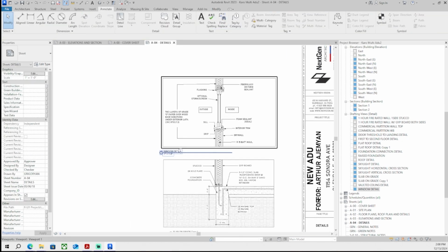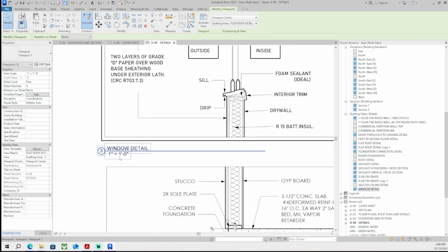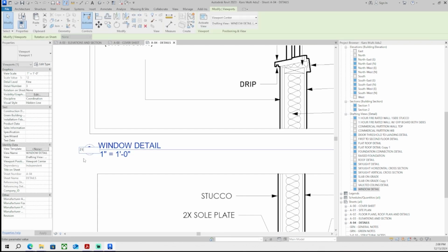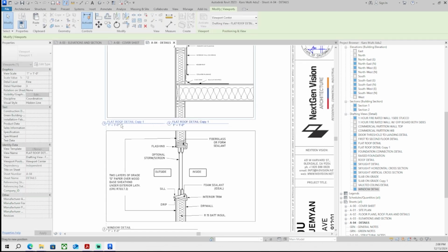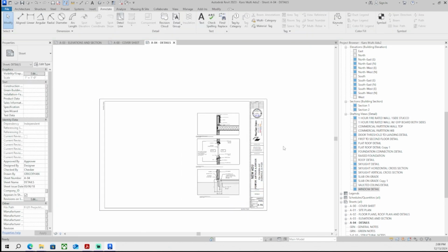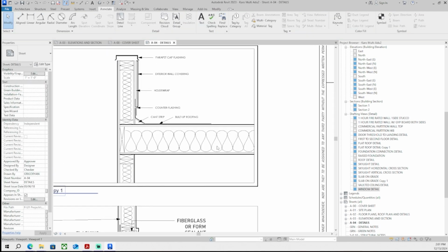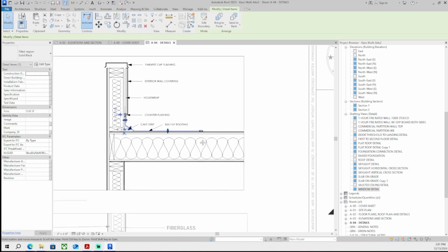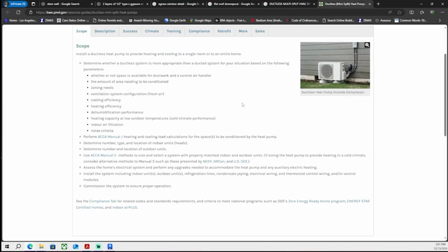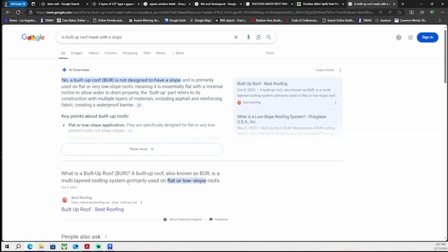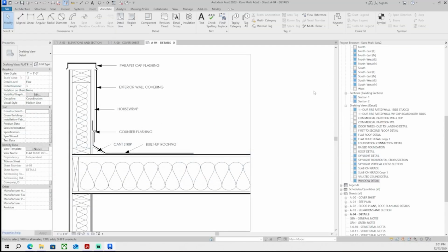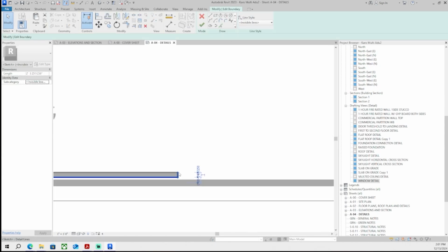But see here, I'm laying out the sheet A04, the detail sheet, and I'm having the foundation detail and the window detail and the roof detail align, so they connect, so it reads as a section, but you see the details. And I think this is the proper way to lay out your details on your detail sheet. Instead of having them just laid out on the sheet randomly, lay them out so they read like a section through the building.